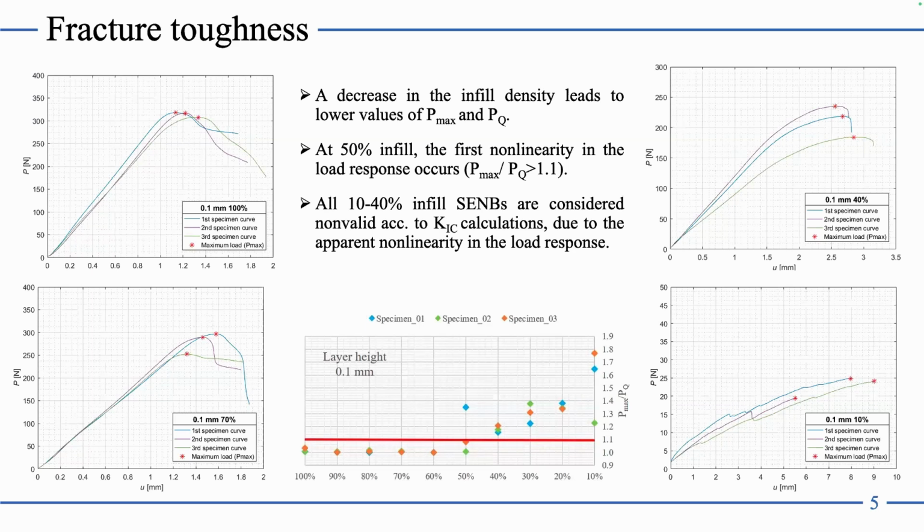we see that one specimen exceeded this value and is invalid for fracture toughness results. But from 40 to 10%, if we look from the higher to the lower infill, we see that this force value condition fails.